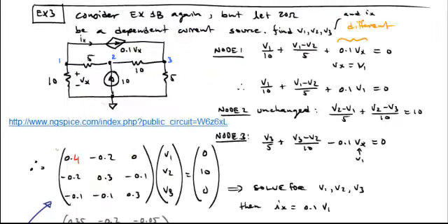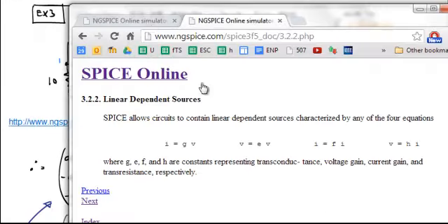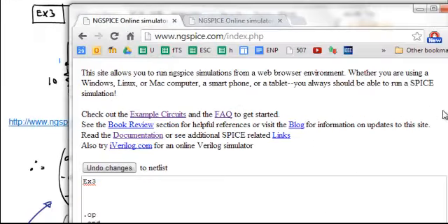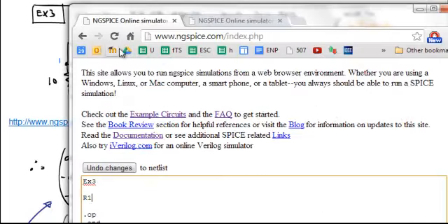Remember, I told you that in SPICE, the way SPICE recognizes a device is by the first letter in the netlist, or in the reference designator. So R for resistor, I for current source, and so forth. So the question is, if I have a dependent current source, what is it? Is it I? Or is it some other letter? It turns out it's a different letter.